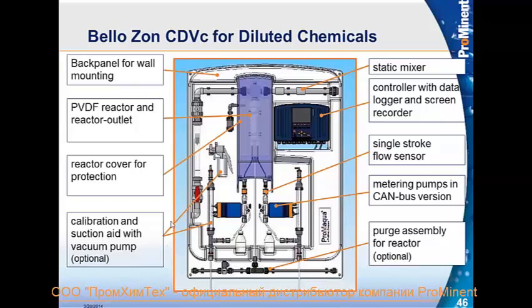There are quite a few safety factors in here. If one of the containers of the chlorite or the acid goes dry, the system shuts down. If something happens to one of the metering pumps, the system shuts down. If the bypass water would stop, the system would shut down. There are quite a few safety factors because with something like chlorine dioxide, you just want to make sure that everything is safe. You also want to make sure that your operators do not mix the chlorite and the acid except in the generator, because mixed together they will create chlorine dioxide gas, which can be explosive.